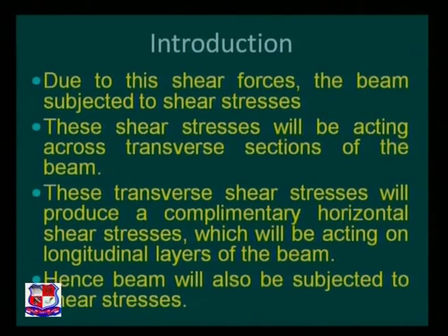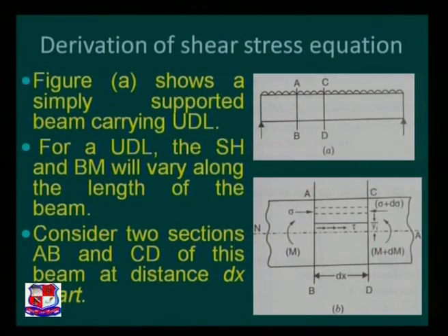These transverse shear stresses will produce complementary horizontal shear stresses which will be acting on longitudinal layers of the beam. Hence, the beam will also be subjected to shear stresses. Now, let us derive the equation for shear stress.